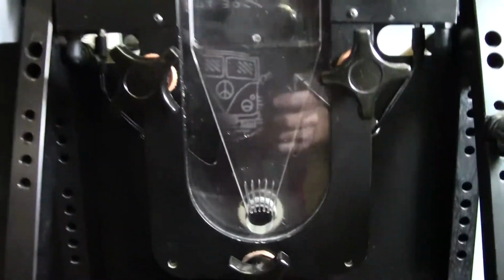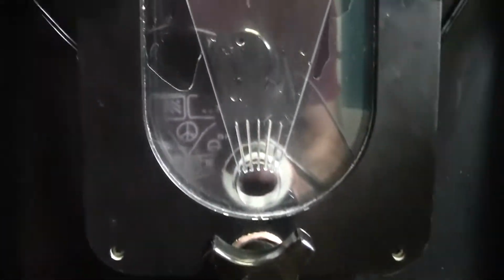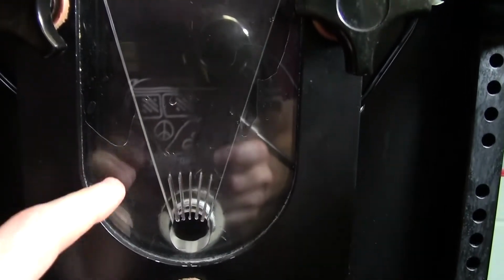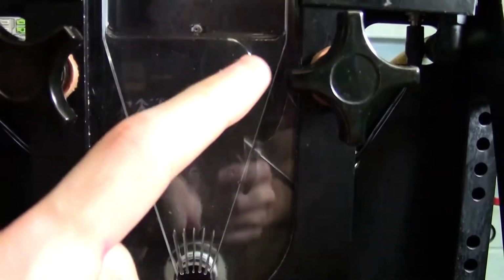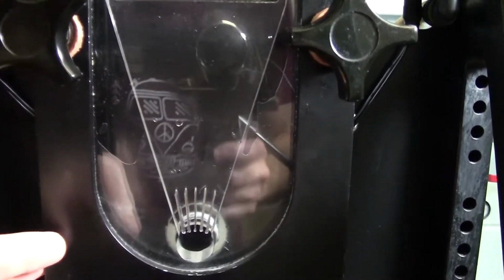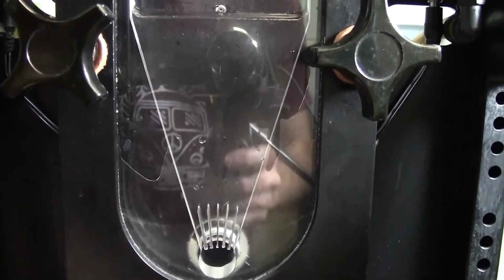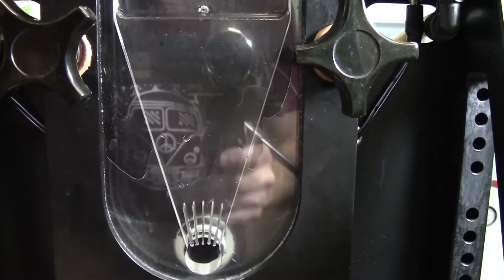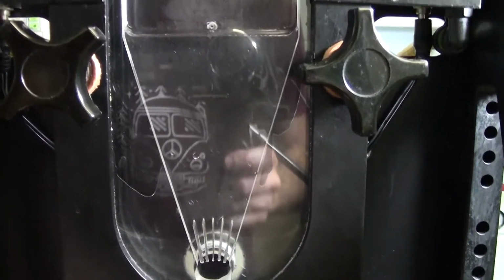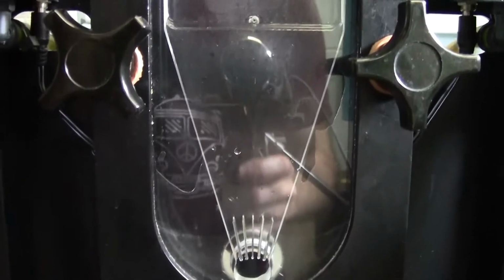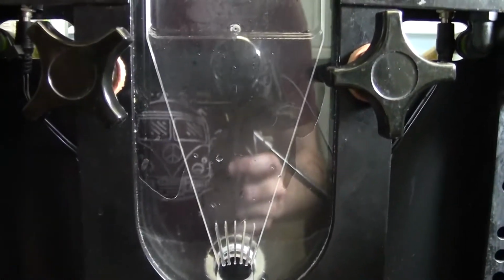Then the water enters this area here. As you can see, we have some vertical fins and an expansion. The fins help eliminate the turbulence in the flow as the flow is forced to go upwards without mixing when it goes through these fins. Also, the expansion helps to get a uniform flow across the whole cross-section.